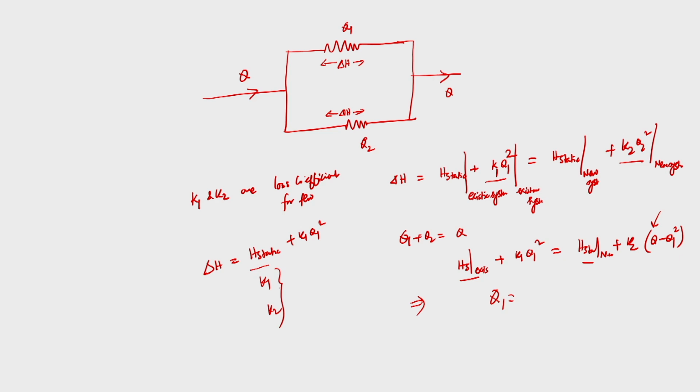So, another aspect is to provide some orifice plate only to kill the head or to increase the resistance. So, either from the existing system we can increase resistance to bring it equal to the new system, or we can reduce the resistance of the new system and bring it equal to the existing system.